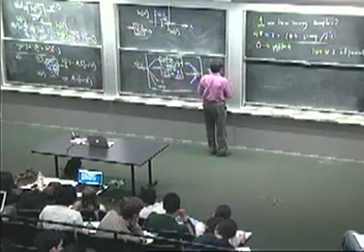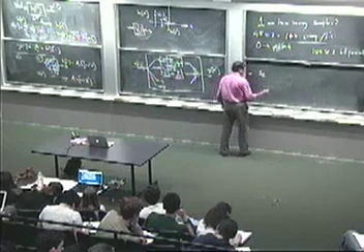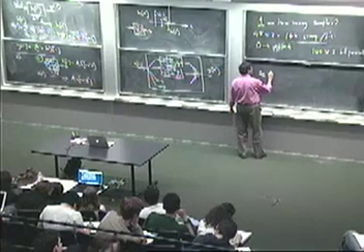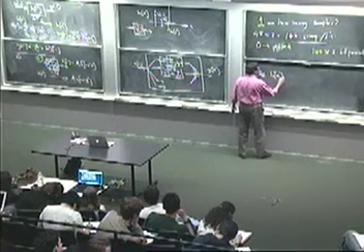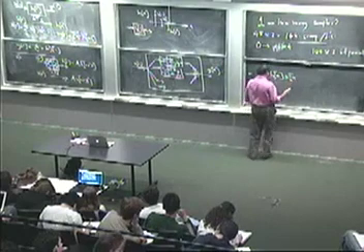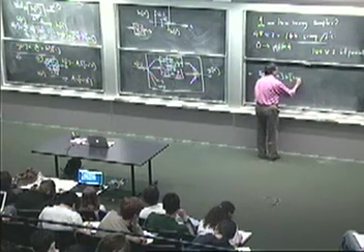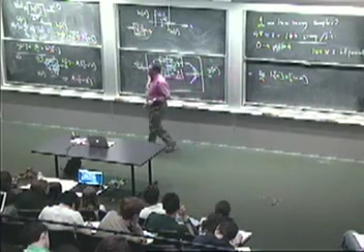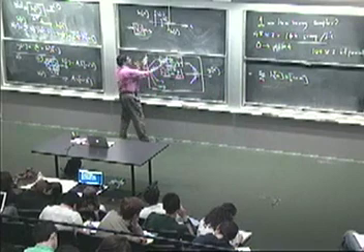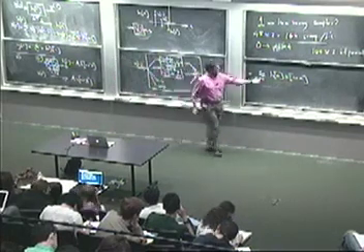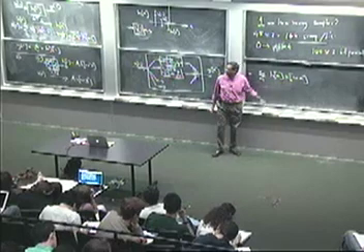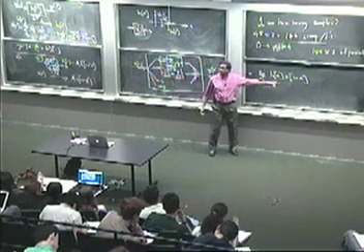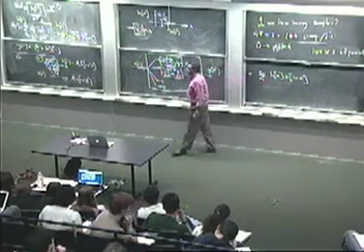So what comes out, y of n, is equal to the sum of h[m] x of n minus m over all m. Okay? So I take x[n], I shift it by nothing, I scale by h0, that's one of these terms, the term corresponding to m equals 0. I take x[n], scale it by h1, delay by 1, that gives me the term with m equals 1. So here's another way to write it.